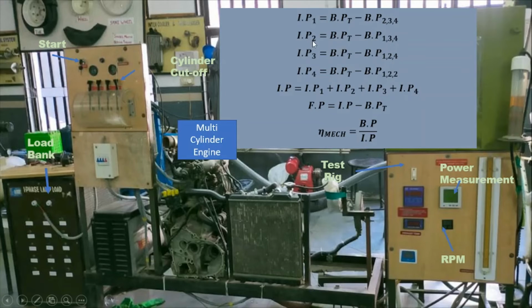Same for the second cylinder: indicated power is the total brake power minus the brake power when the second cylinder is cut off. Same for 3 and 4. Total indicated power is equal to indicated power 1 plus indicated power 2, indicated power 3 and indicated power 4. The friction power is the indicated power minus the total brake power. Mechanical efficiency is the brake power upon the indicated power.